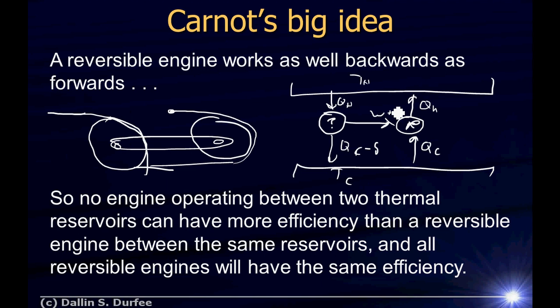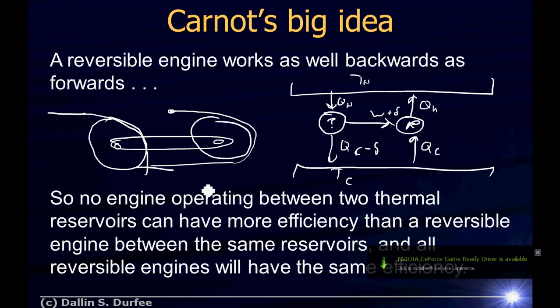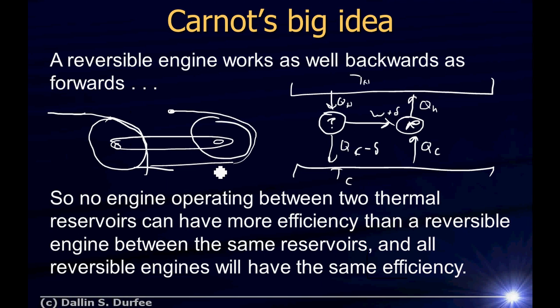So basically, if you had a reversible engine and then you found one that was more efficient than that reversible engine, the two of them together could spontaneously make heat flow from something hot to something cold. It would be like saying I have an ideal reversible water wheel and then I have one that's even more efficient. I have a little water go down and I bring even more water back up. So this device with no energy lifts more water than went down. So spontaneously water is going from a lower place up to a higher place.